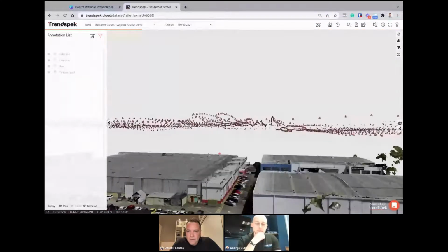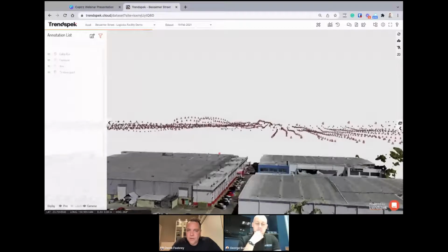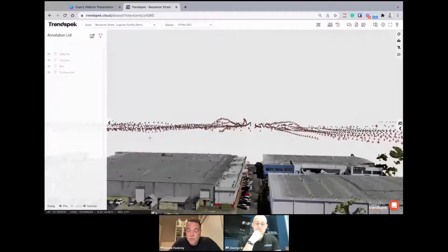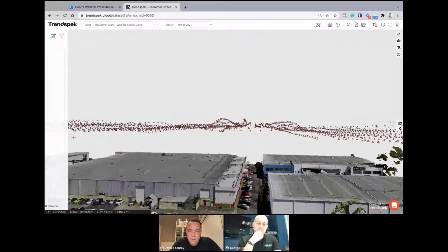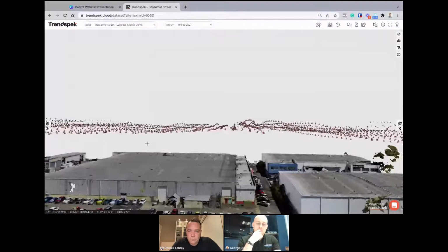But what will happen with the more consumer drone, the non-RTK one, is you might fly at the same height for every flight, but your recorded GPS position, especially in the Z-axis here, will show one flight in line, the next flight it'll think it's 50 or 60 meters higher, and the next flight will think it's below ground, which makes everything really challenging trying to line things up.